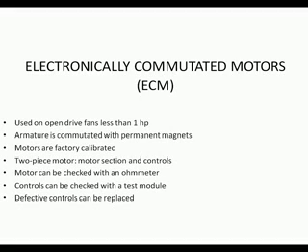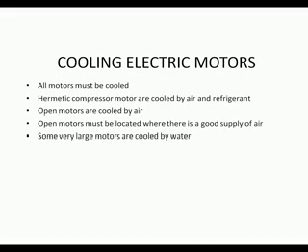The inverter varies the frequency to obtain the desired speed. A 6-step inverter receives voltage from the converter, and it controls the voltage and the current. A pulse width modulator receives fixed DC voltage from the converter, and then the voltage is pulsed to the motor. It has short pulses at low speed, long pulses at high speed.